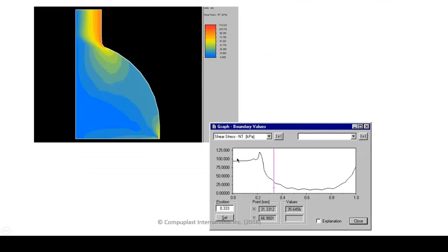So here is the high stress in the adapter region, and then you can see the shear stress reduces down to this valley in this region right in here, and then comes up again just near the breaker plate because the flow off the breaker plate is essentially a plug flow, and then that plug flow with a constant velocity is changed to a parabolic flow as it moves down into the adapter. And so we end up with this low shear stress region right in here, and this is our line showing our 30-35 kilopascal design value recommendation.